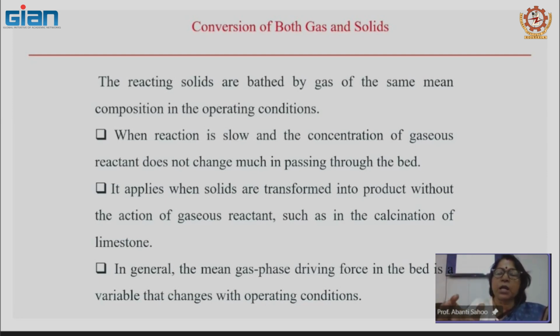So, with that force, it will be moving up. Thus the reactant does not change much when it is moving upward. When solids are transformed into the product without the action of the gaseous reactant, such as the calcination of limestone, both gas and solids are converted, and the mean gas phase driving force in the bed is a variable that changes with operating conditions.